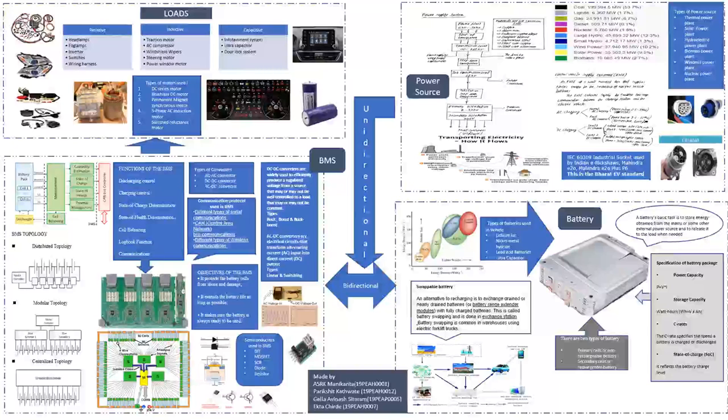And if we take one wire from that and one neutral, then it will be a single phase. If the load is high, then we can take three phase. If we want more load, three-phase will be preferred. If not, up to 7 kilowatt or 7.5 kilowatt, one phase is enough. Beyond that limit, we need to use three-phase system.